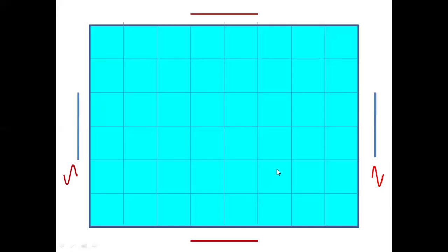When the X plates are connected to the alternating supply or the time base is on, a horizontal line appears on the screen. And the horizontal line here is appearing in the middle because no connections are given to the Y plates. If the upper Y plate is made positive, what will happen as a result? The horizontal line will shift upwards. The beam is oscillating along the horizontal as well as having moved upward, depending on the supply voltage to the upper Y plate, how much positive the upper plate is made.